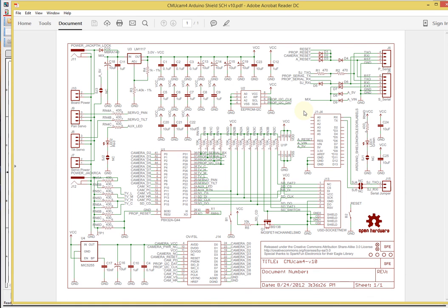I know that this makes sense to the person who's drawing the schematic because you drew it and you know where everything is, but when another person is looking at it, they have to search through this schematic and waste time because this is not clear. Another motivation I believe this comes from is trying to pack the entire design into one single page, as if pages were a scarce resource, especially when you're going to supply the design in the form of a PDF.